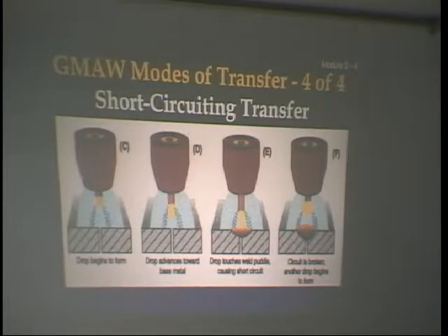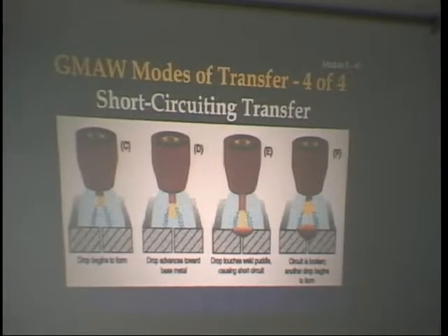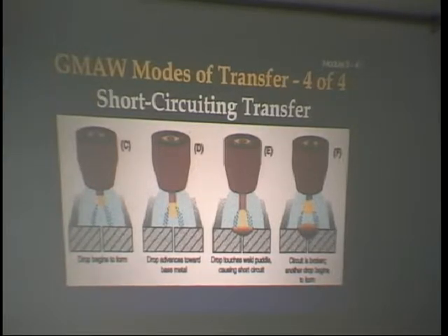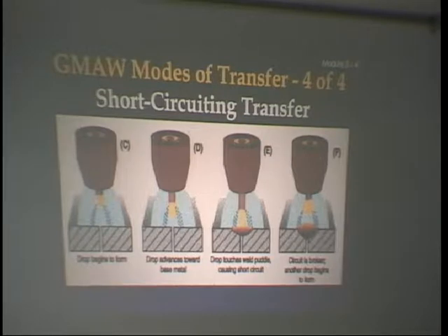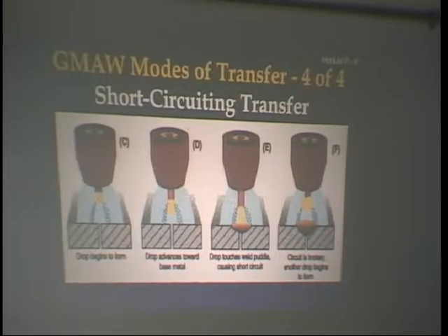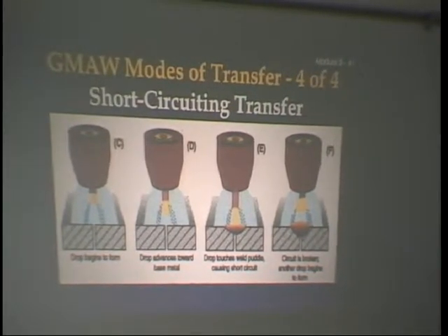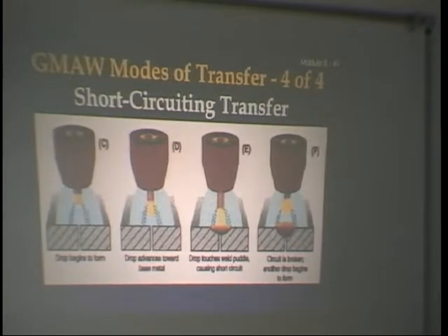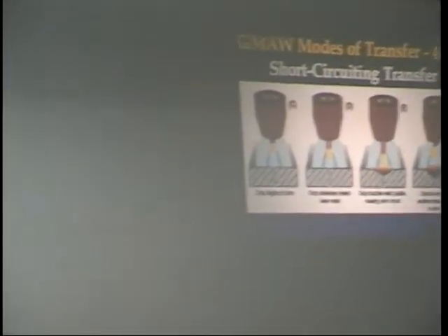So you should have bullets for open arc method, short circuit method, spray transfer, globular transfer, pulsed arc. And on page 755 where it says short circuit transfer, GMAW-S, you should have a bullet there. Know why there is no metal transferred across the arc in the short circuit, because it actually touches the metal. On page 756, understand what pinch force is. Pinch force. Okay.